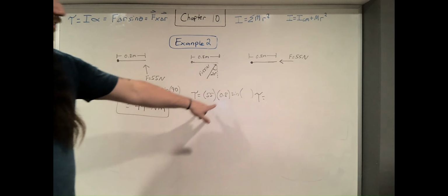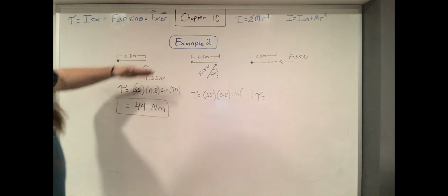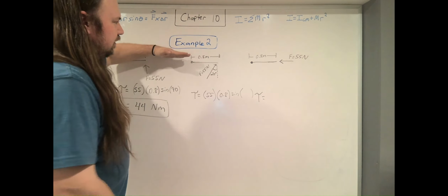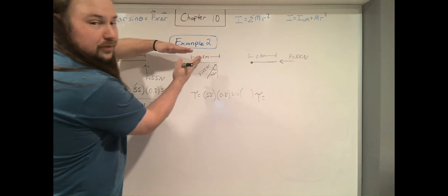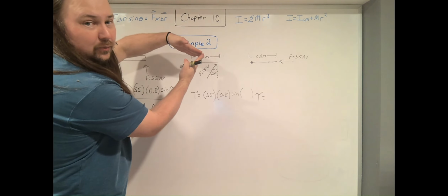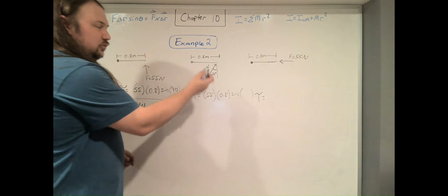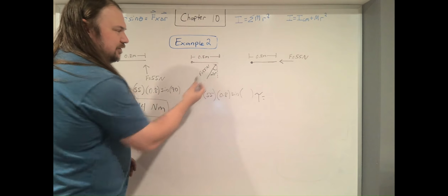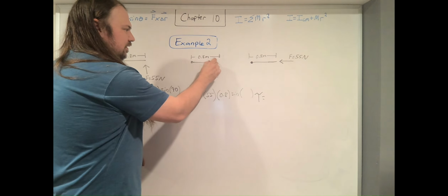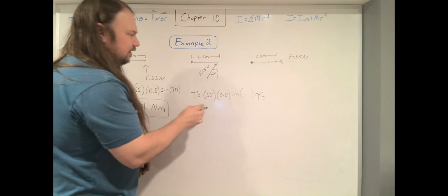I want the angle between these two vectors. Okay, I want the angle between those two. Radius of the door remains horizontal. The force, though, has now been moved 20 degrees. So the force is coming at about a 20-degree angle. What angle is in between those two vectors? It is not 20. 20 is the difference offset from 90, right? The angle between this arrow and that arrow is the rest of it, 70 degrees.